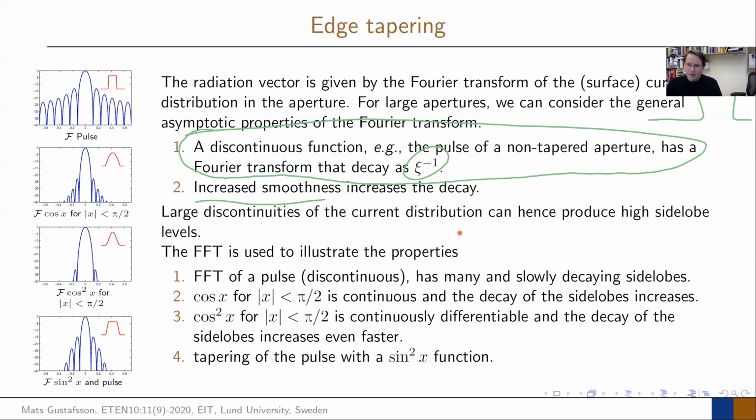And if we look at then the FFT, or the Fourier transform in these cases, maybe not the fast one, it doesn't matter. We can see the example here. Here you can see this rectangular shape as you had for array antennas, and now we have it here. If you take the same distribution and you smooth it, here you can see the side lobe levels then go down. And that's the same thing as happening in the Dolph-Chebyshev, binomial array and so on. You take them away by making it smoother and smoother. So in this case, it was a little bit smooth because it's a cosine. If you do a cosine squared, it's a little bit smoother, and you see it's down even more.